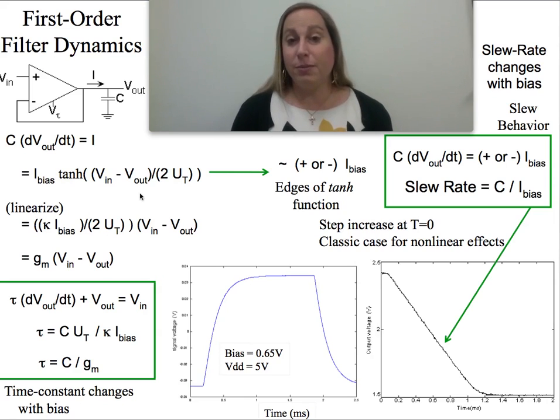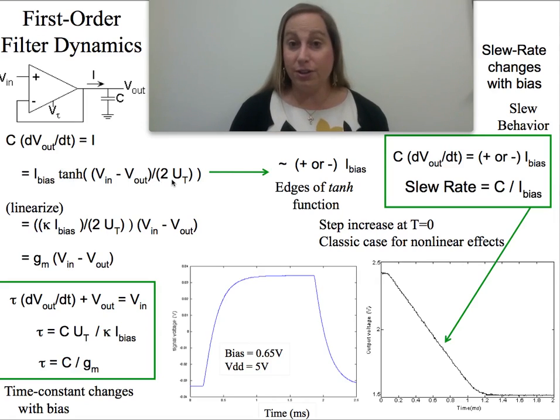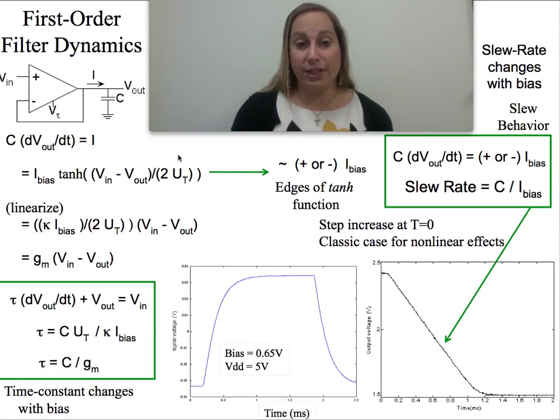There are multiple places you want to look. The first one people will talk about is what happens when stuff is small. We've even talked about small signal models to some extent. But this gives you a really solid idea of what we mean when we talk about small. In this case, what you see is we have tanh of a whole bunch of things. The tanh of this, when it's near zero, near the middle of the tanh, is roughly just that term. So if I linearize the tanh, it just gives me what's inside here.